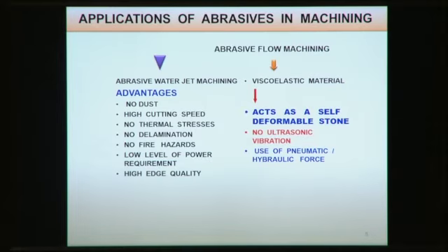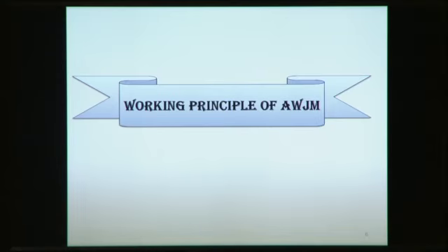Low power requirement is another advantage of abrasive water jet machining, and high edge quality is also observed in the abrasive water jet machining process. Now, what is the working principle of abrasive water jet machining? Here we can see that the abrasive particles are coming at an angle and attacking the surface.